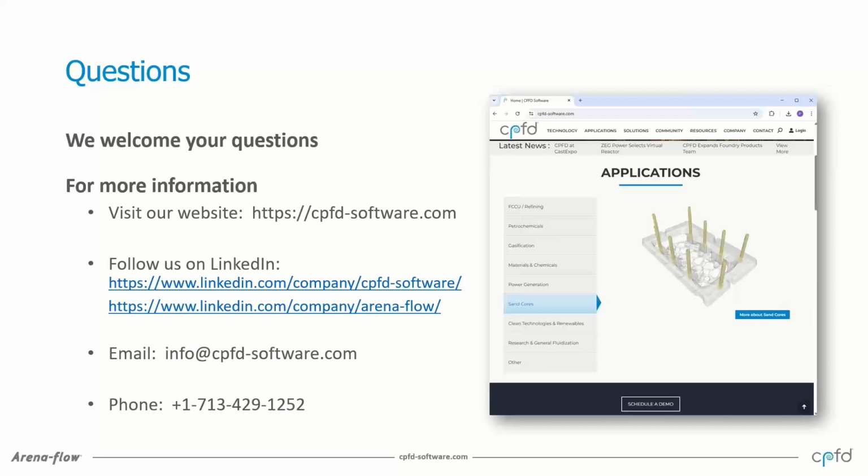But because Arena-flow handles the sand separate from the air, so it's not one Eulerian phase for the CFD folks, the particles are discrete, gridless. We use far coarser grids than you would use for most computational fluid dynamics, and as a result are able to capture things with far less mesh sensitivity. And this is something that we can work with you on, especially during a training, initial project or quick start, where Thomas can work with you or our team and run that grid sensitivity study like you would do. But it's surprisingly not terribly sensitive.